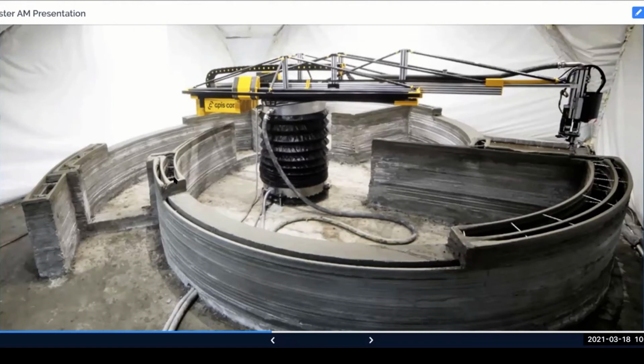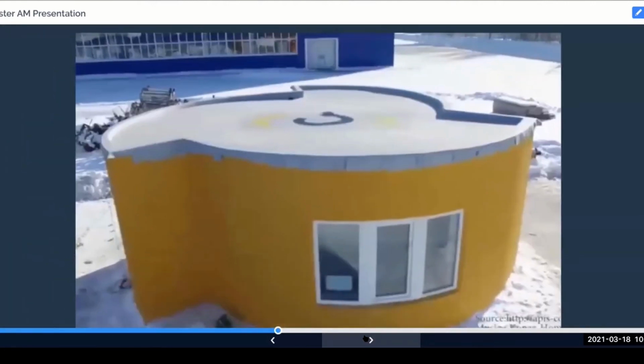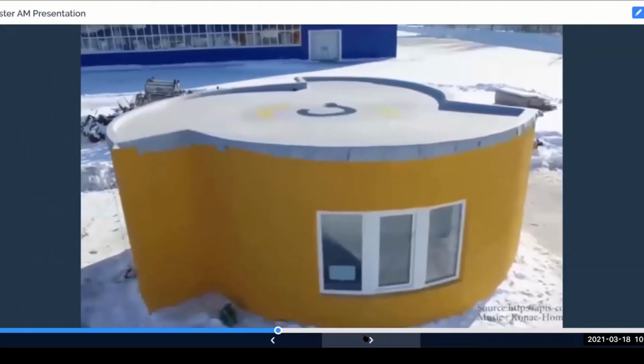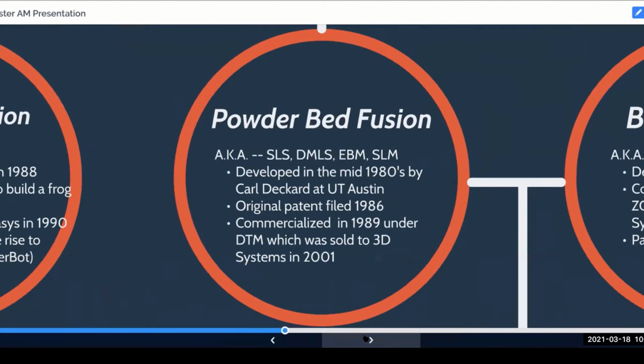You just have that gantry in the middle, and it can create this geometry as you go. The only issue is here we're really thinking more like mass masonry construction. You're laying these layers of concrete on top of one another as you go. You have really poor binding conditions between those two layers. So it's not going to be really robust concrete, but if you make this thing big enough, it's just like laying stones on top of one another in your backyard, right? So you get a pretty good structure from that direction. So anyway, that's kind of cool and exciting from the additive side.